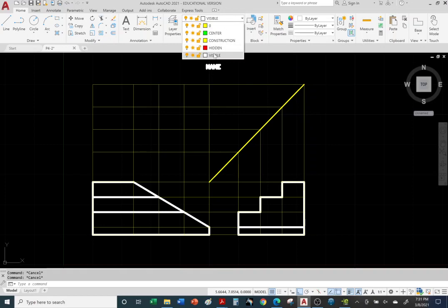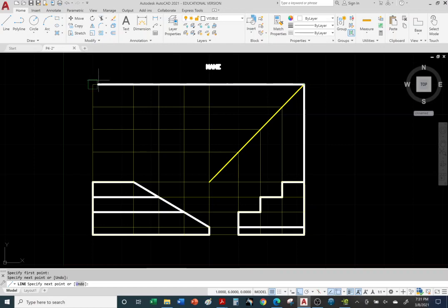All right, so we are in the visible layer. Okay, so let me use the line command. And from this furthest right corner, I'm gonna go straight up, hit the 45, and I'm gonna go across. And then I know I gotta line up with this one. See that? I gotta line up with this edge, the furthest left, most extreme point on the front view. Click.